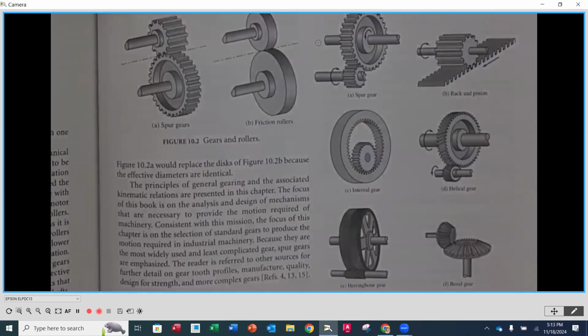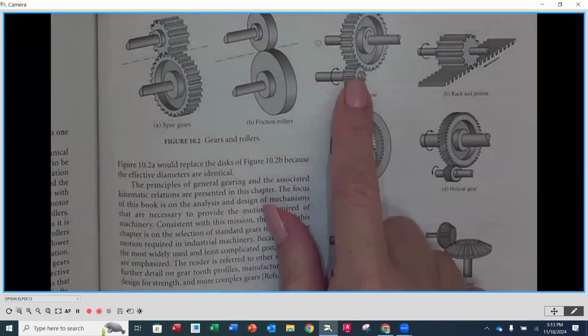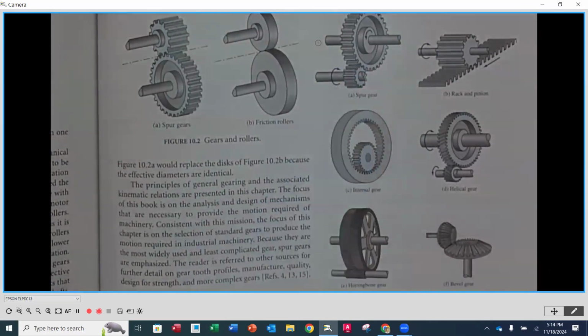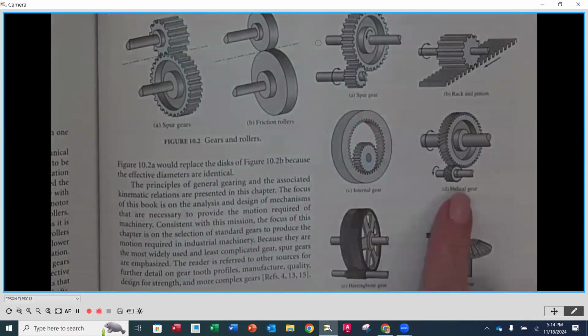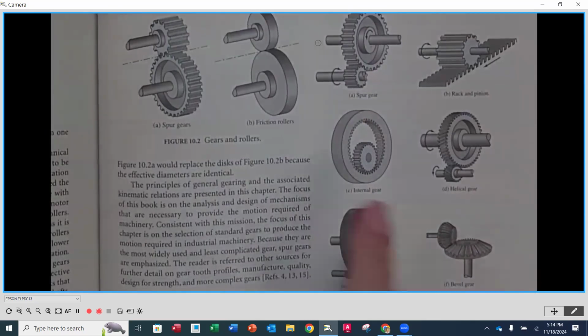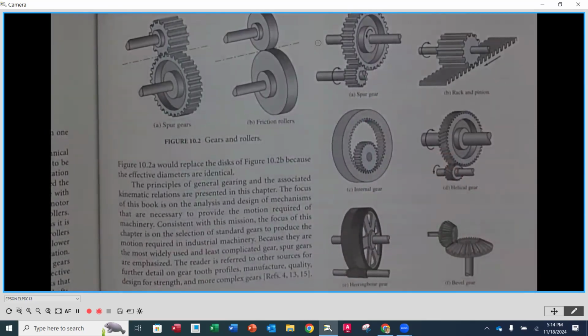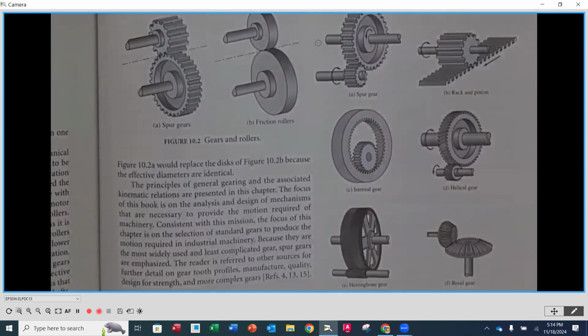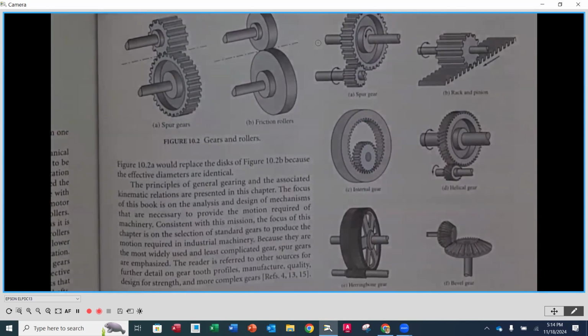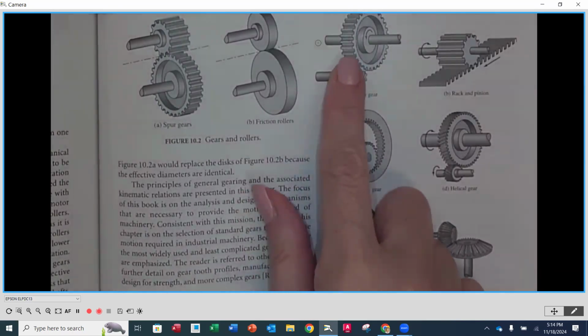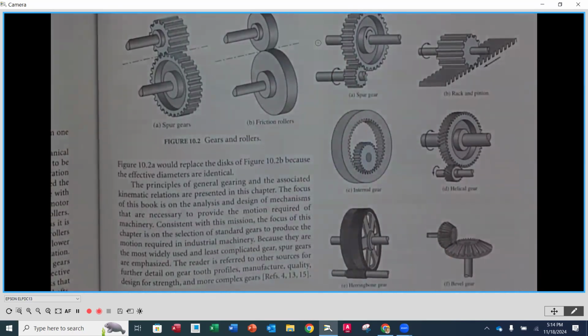So you end up having a quieter gear set because you don't have one clanking on the next, because spur gears are notorious for being kind of loud. So they're a quieter gear set first and foremost. Second of all, for the same face width, which is the thickness of the gear, you get more line contact to actually transmit your forces, motion, and torque through, which means that it can take higher loads as opposed to just having the length of the width of the face width.